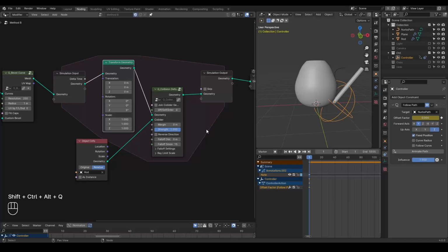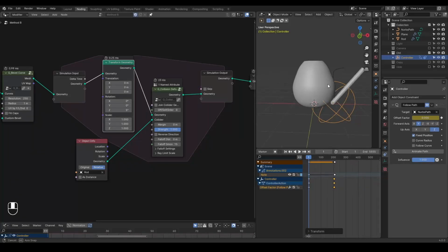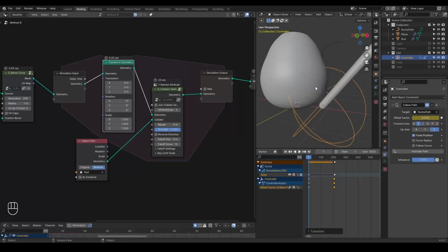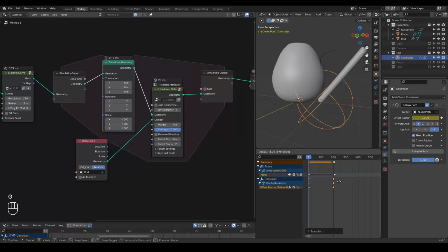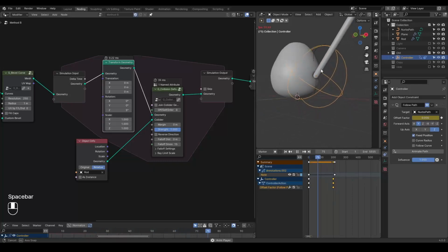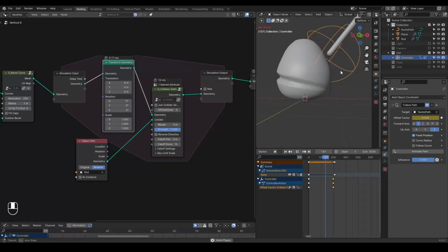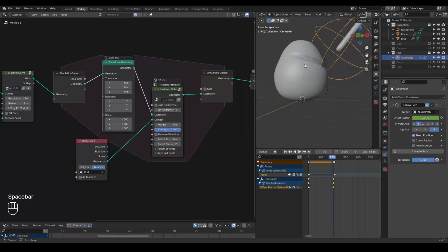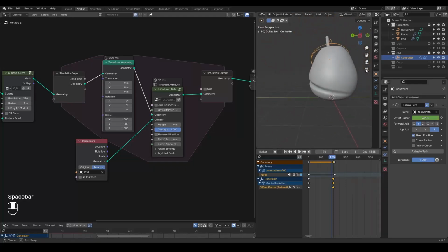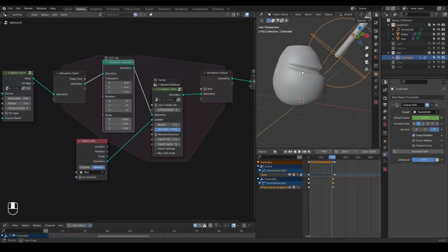Here it's possible that people do not want to render 400 frames. They want to speed up this entire process. So you can change the keyframes to 200 frames, so 2 times. Then you play this animation, and you can realize that because it's running too fast, it's not finishing a cycle.